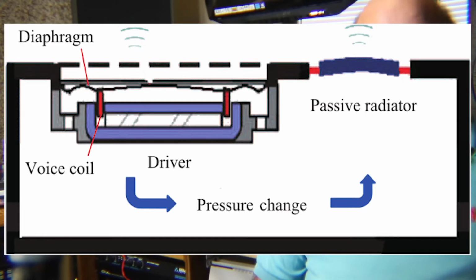Although not very common in sound reinforcement products, there are devices which look exactly like speakers placed inside of cabinets, which are referred to as passive radiators, which lack a voice coil. It's basically a speaker minus a magnet minus a voice coil. They radiate sound by sympathetic vibrations from within the cabinet. Some consumer speakers and a small number of studio monitors utilize these.